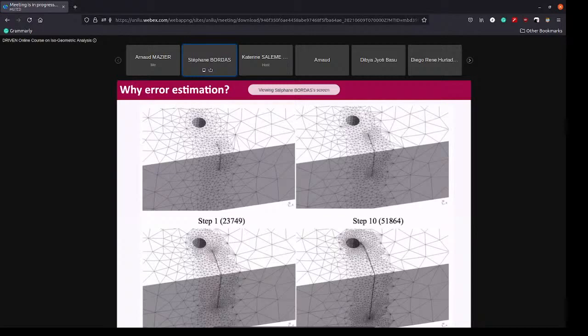And just so you know, if you do not use mesh refinement, this probably will partly answer the question that you were asking before, which I thought was very sensible. If you do not have local mesh refinement, then it means that you need to predict before the crack propagates where the crack will propagate, which by definition you don't know, because otherwise you wouldn't be solving this thing. And so you would need to refine like crazy this whole region with extremely small elements, and then let the crack propagate, hoping that you have enough elements. So this is a bit brute force, honestly.